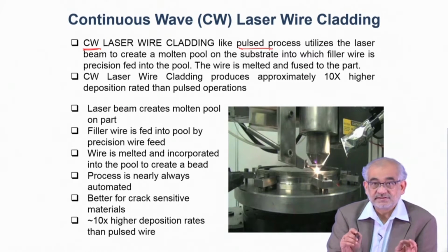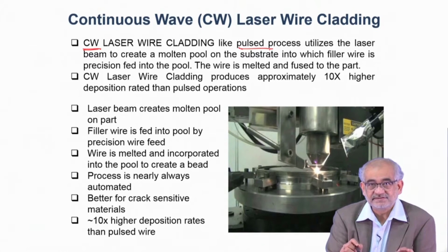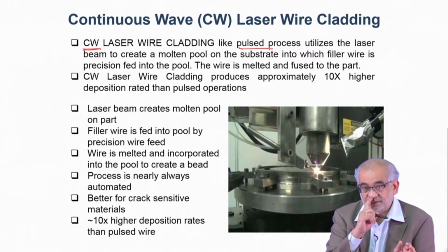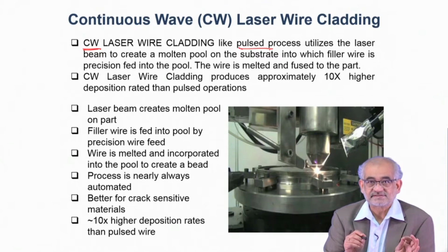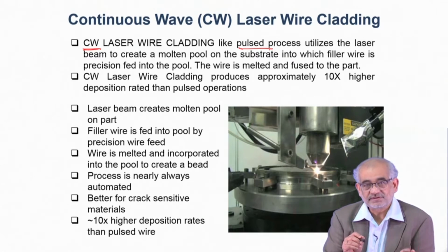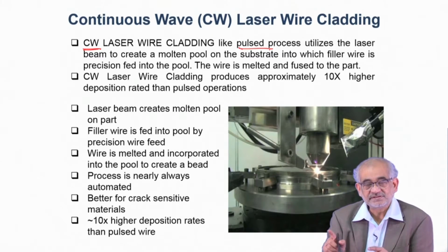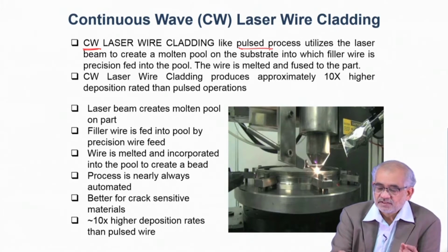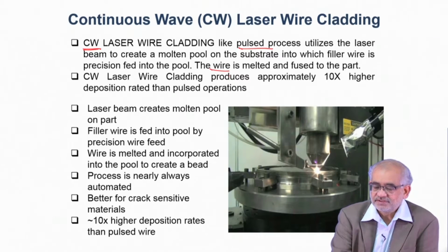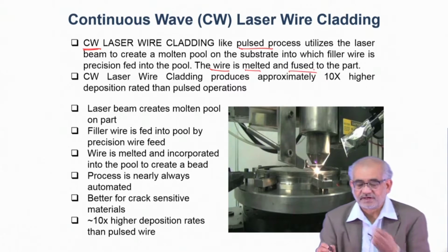The application of energy through this kind of laser is very precise. We know exactly what thickness of material we are able to deposit because we know two important parameters, the power density and the interaction time. Usually we feed in the form of wire, or even powder, into the laser beam, which instantly gets melted and then fuses to the part.